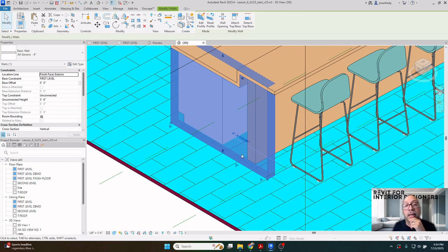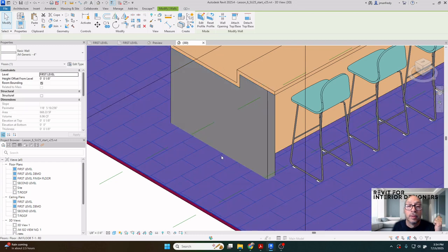And in this case, there are several different ways of doing this. You can model it in 3D as a razor-thin object that traces this wall on all sides and is the appropriate height of a base. You can do the split face command and carve out an area at the bottom of this wall, on all sides, that can be painted with a different material to create the base.